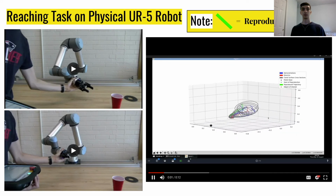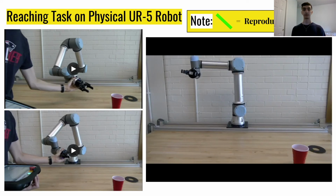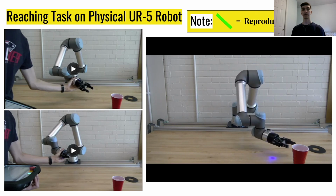moved. We use the recorded data to create a canal surface and then reproduce the motion based on an arbitrarily chosen starting position. The same color scheming is used, with the green line representing the reproduced motion, and then we execute this motion on the actual robot.